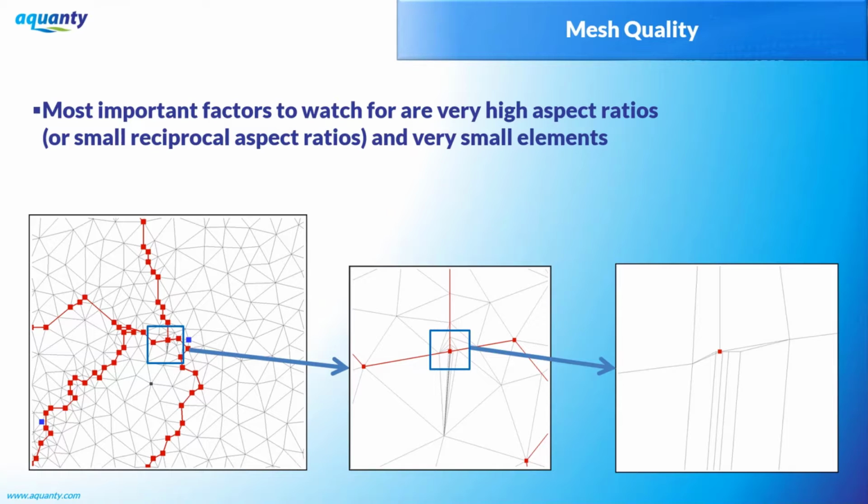Quite often, bad triangles or areas of over-refinement are fairly obvious, even just when visually inspecting the mesh. However, there are a few quality metrics that are available to us, both within AlgoMesh and HGS itself, if we want kind of a more quantitative look at mesh quality.